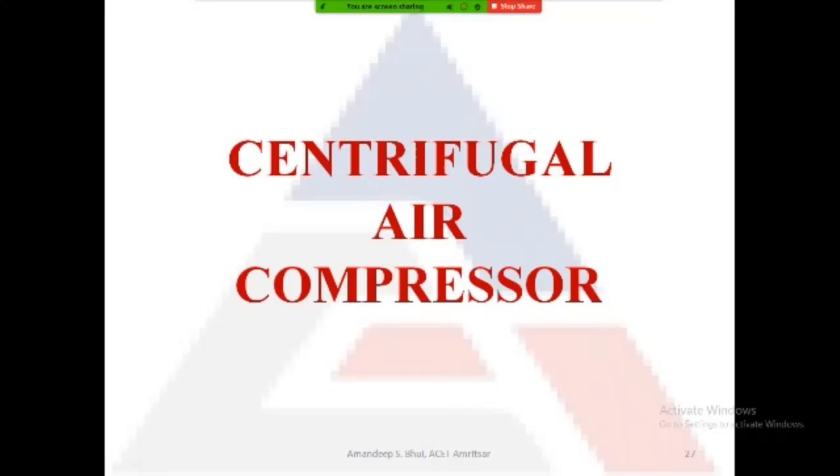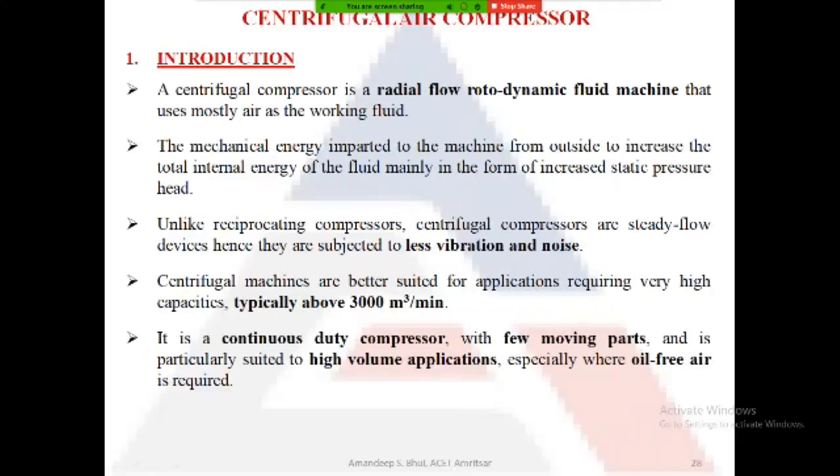Okay. So at the front, the air is slow, and from behind, high velocity air is coming out from the rotor side. This high velocity air pushes the particles of the slow air, and when those particles get pushed, they come closer to each other, and because of that movement where the particles come in close contact with each other, the compression of air takes place. Because of this compression, the pressure of the air increases. Okay, now this is the basic working of a dynamic type of compressor.